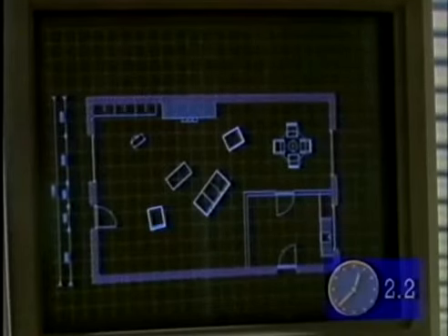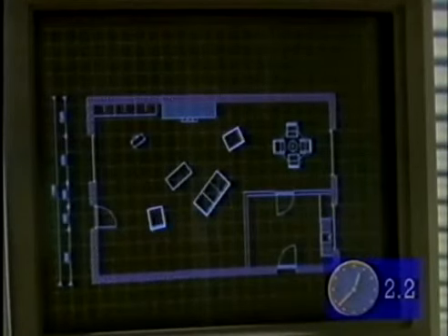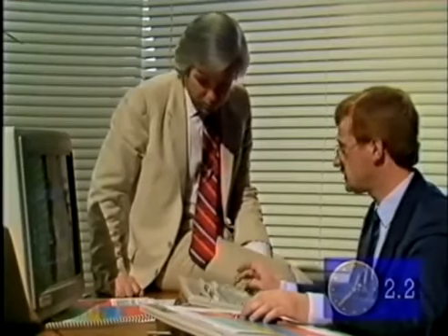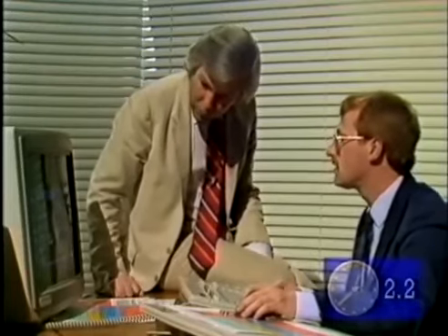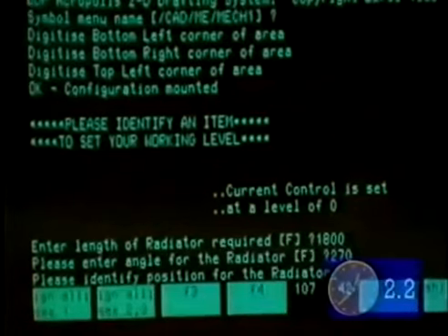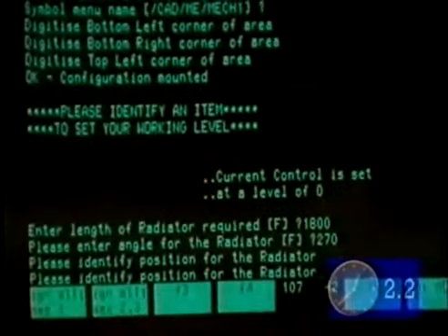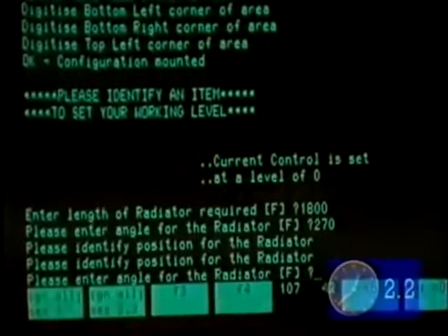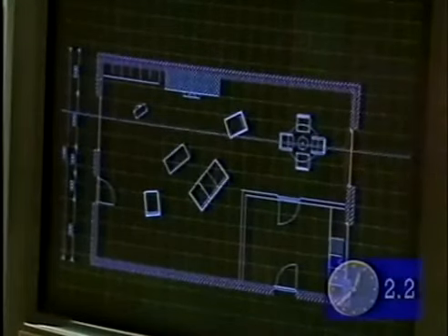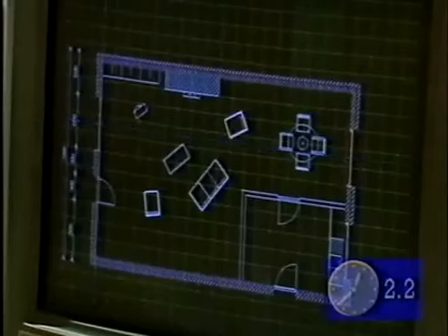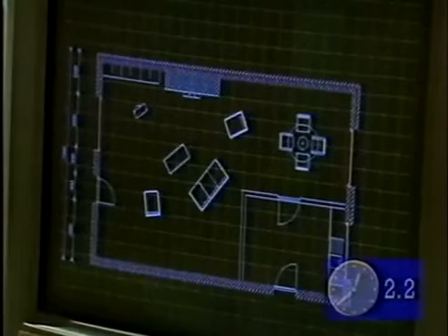And it's now asking me for the angle, because again, once you create a symbol, it comes in a certain way. So what it needs to do is know the angle of it. And if I type in 270, we can put a radiator in there. Now, it is centrally justified again. Right. And in goes that radiator. Yes. Okay. I can then re-change the angle, and let's go to 90 degrees. Right. So this is the orientation of the symbol. That's right. And put another one there on the drawing. Mm-hmm. And that is how you tend to put in those radiators.